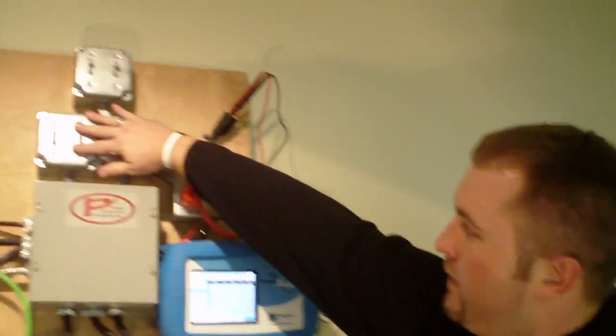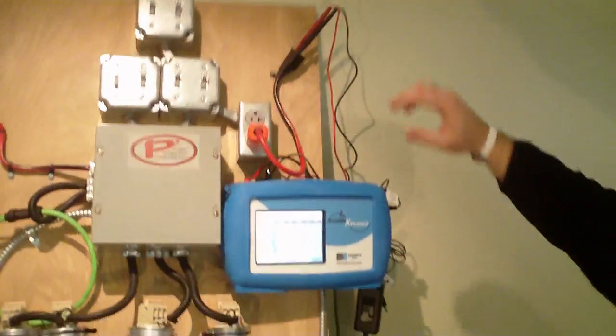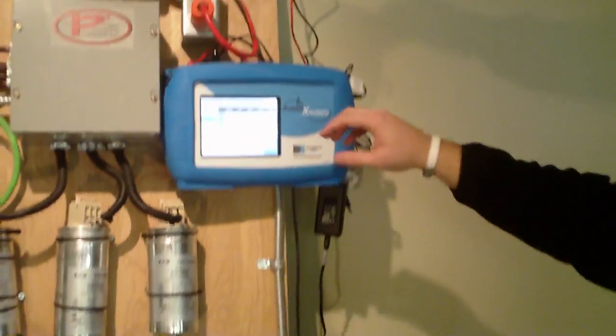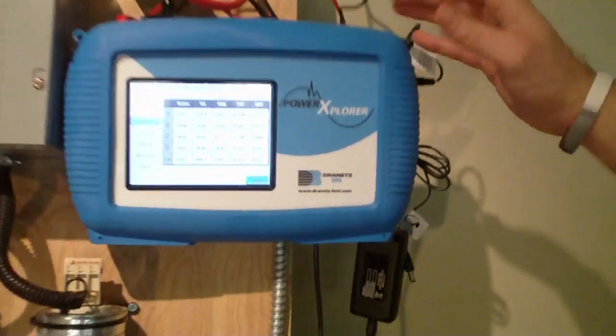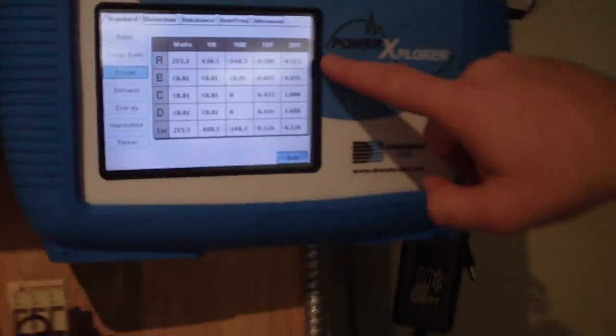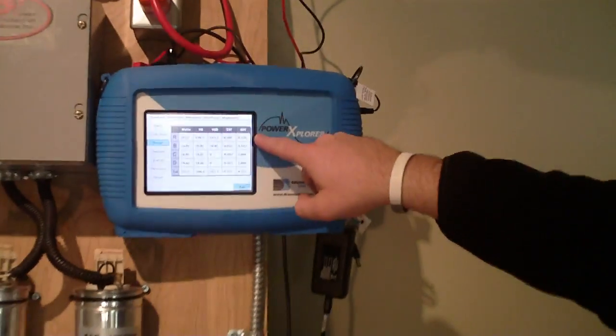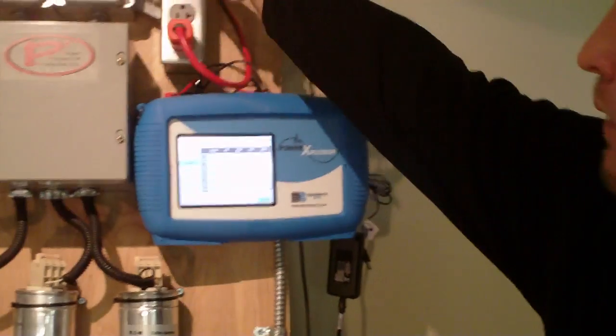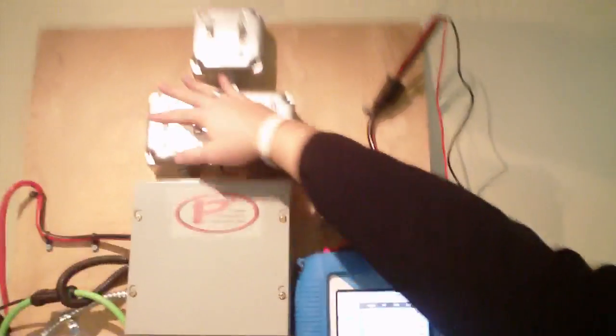I will now bring on the last stage, and you can see we went from an inductive power factor, or lagging power factor, to a leading, also known as capacitive, power factor. And we are injecting more kVARs than we're actually consuming. I will now bring on the second motor to show you we can bring down the power factor again with another inductive load, a 0.60.